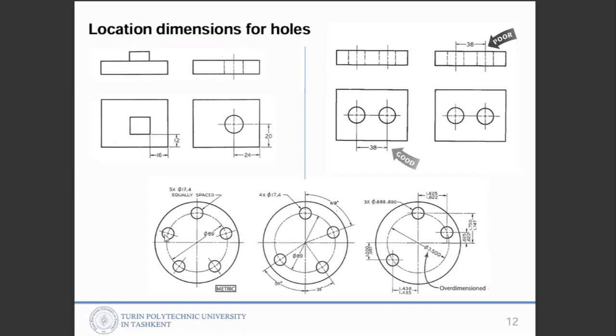The crossing of these two chain lines gives us a center for the hole. So one hole, and then from here to here another 72 degrees, and the crossing will give us the center for the circle, another 72, and then find the center and draw the circle.